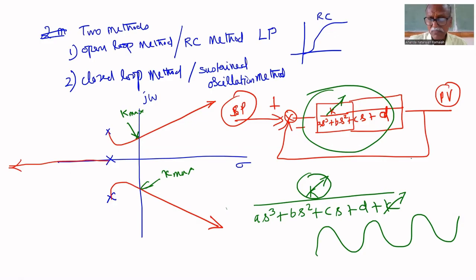Because you put three phase shifts here, 60, 60, 60. The components that you are using have how much tolerance? 10% tolerance. If you get 1 kilo ohm, it may be 900 ohm to 1100 ohm. Sometimes 5% tolerance means it varies from 950 to 1050.